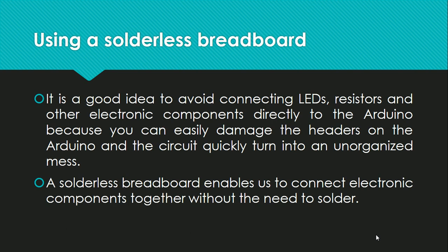Okay, so after setting your work area, we have this component that is very useful and very important in prototyping: the solderless breadboard. It is a good idea to avoid connecting LEDs, resistors, and other electronic components directly to the Arduino because you can easily damage the headers on the Arduino and the circuit can quickly turn into an unorganized mess. So that's why it's never a practice to directly connect the electronic components to the Arduino.